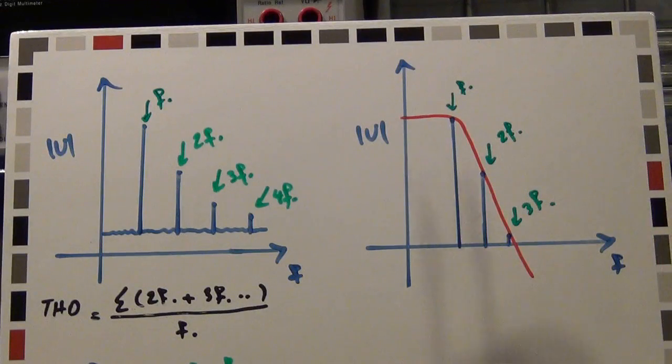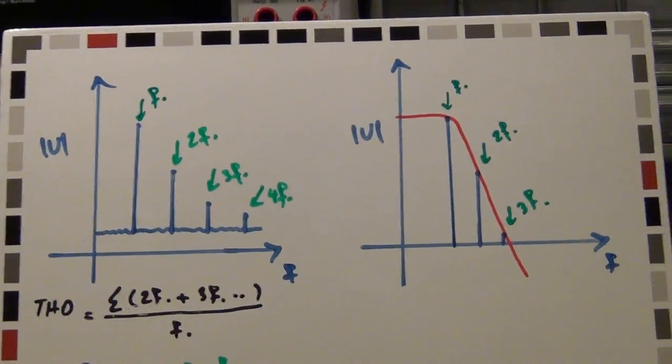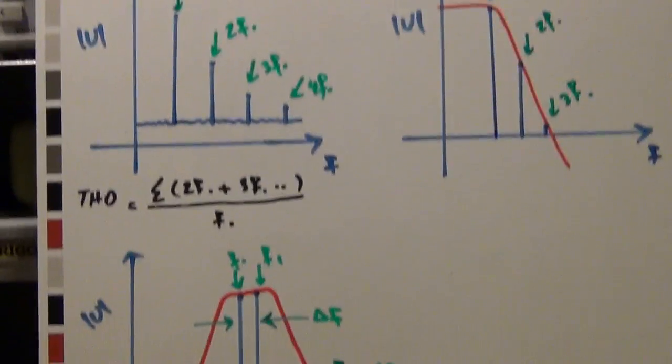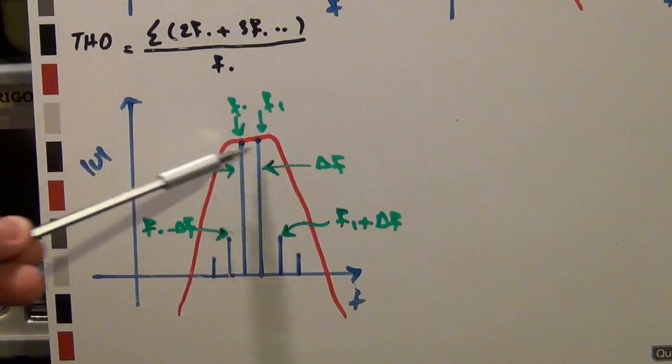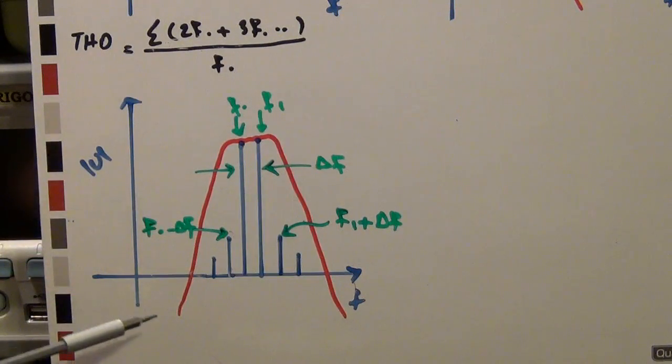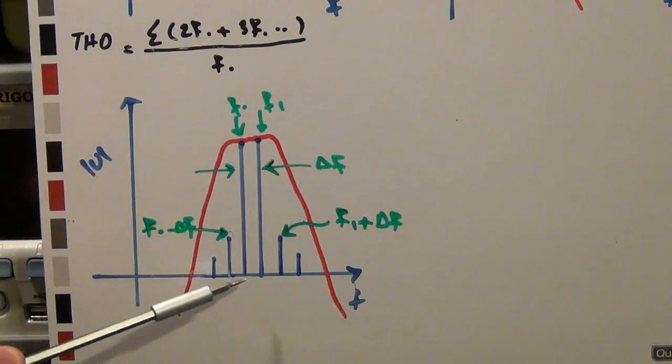So in order to avoid that, how people measure total harmonic distortion, or for wireless terms, how they measure the third order intercept point, which I'll talk a little bit about, is that they put in two tones at the same time instead of one. So here's an example of a wireless receiver. So I say wireless because it has a bandpass response. So for example, let's imagine this is a Wi-Fi signal around 2.4 gigahertz.